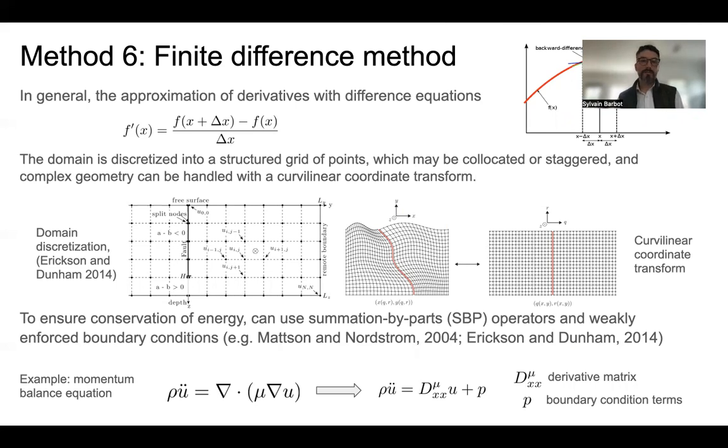So one way to do this is to consider a rectilinear mesh, a logical mesh that is mapped to a system of coordinates that maps to a curvilinear fault geometry and mesh geometry. So even though simple finite difference operators are engaged, this method is amenable to realistic structural settings with curved faults and complex structures. And so the governing equations translate into algebraic operators that can be solved with various known techniques.